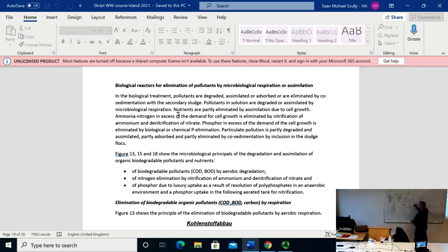So in the COD we have, you have to divide it by 100. So it's 0.4, you multiply it by 2.5. So it's 1 gram of N per day. And it's 0.4 times 0.5, it's 0.2 grams of P per day, right?